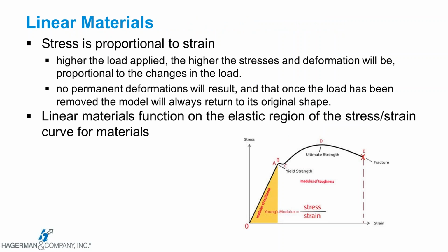So the last piece of this puzzle is the linear materials, or using a nonlinear material in the space. And in a linear environment, linear materials are essentially proportionate to the strain, right? And if we keep ramping up the load, the stresses and deformations will simply proportionally change along with that value. So in my case, on that first analysis, we had a deflection of 0.067 inches at 1,000 pounds. If I were to multiply my load by a factor of 10, I'm going to get a deflection multiplied by a factor of 10. Realistically, though, that's not really realistic to our models themselves, right?